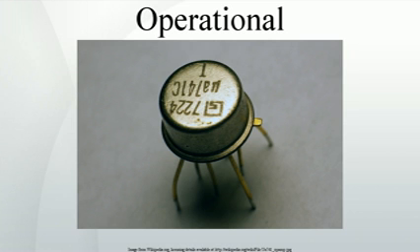However, this first IC did not meet with much success. Issues such as an uneven supply voltage, low gain and a small dynamic range held off the dominance of monolithic op-amps until 1965 when the μA709, also designed by Bob Widlar, was released.